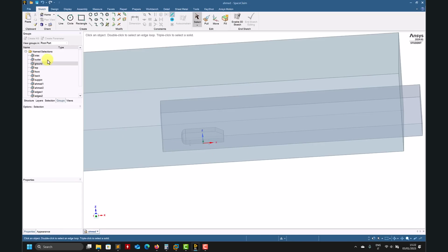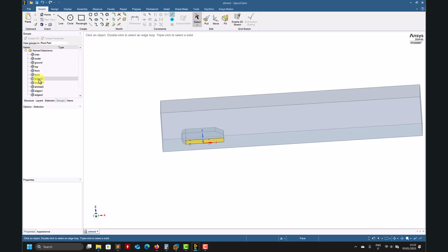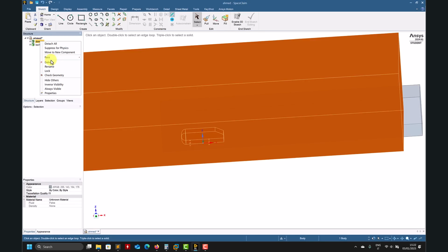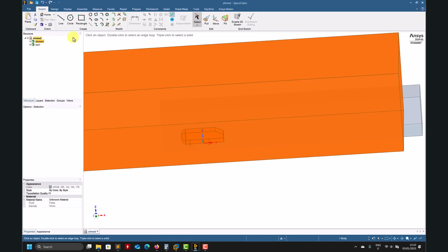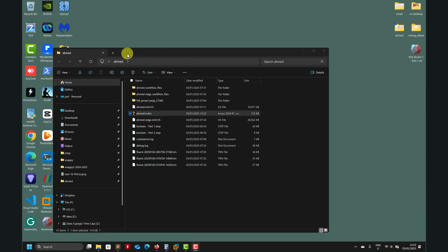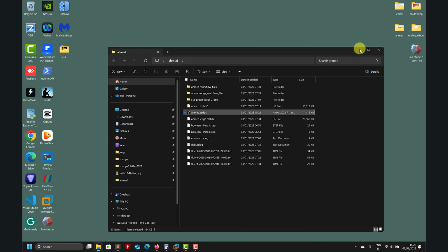Remember that you can also go here and hide the surfaces and so on. This one I misspelled there, should be support. Then here you can also hide it and you have that single body. So it's up to you, okay? For our purposes, let's show everything. Save. And this will be my geometry, okay? This is what I will use in Fluent Meshing to create a mesh, and I will try to reproduce something as close as possible to what we did in Snappy.